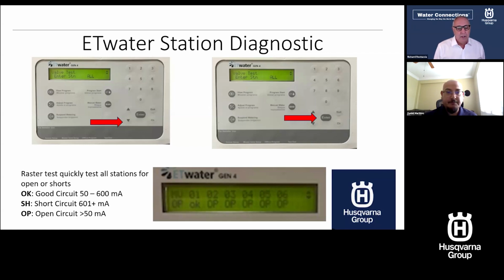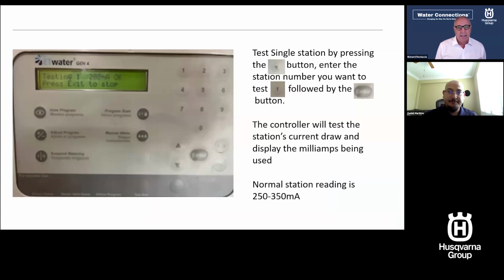Yeah, because it would be unusual to have this situation on the screen. So again, probably the common. Correct. You're having 1 or 2 shorts here and there, maybe an open if there's a station missing or a cut wire. But if you're seeing them all open, then you've got a bigger problem. Usually it's just one common circuit issue affecting all of them, because all your station wires share one common wire, which is our ground circuit, and then they each get an individual station wire.